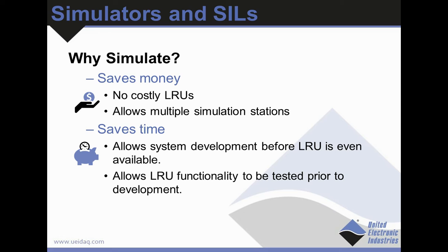Other ways it saves time is it allows you to develop system development before the LRU is even available. You can find out how a proposed LRU works in a system before it's even developed, and probably fine-tune the LRU's capability before you actually have to finalize even the design in some test. And also it allows the LRU functionality to be tested prior. It says development on the slide, but certainly prior to installing into the aircraft.